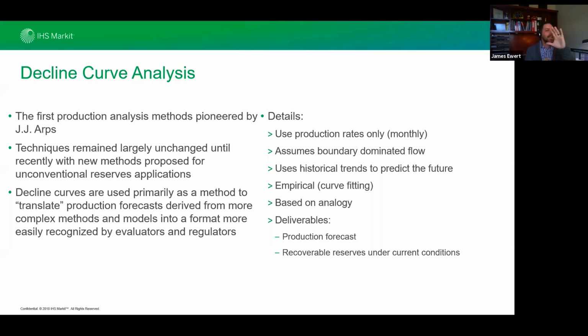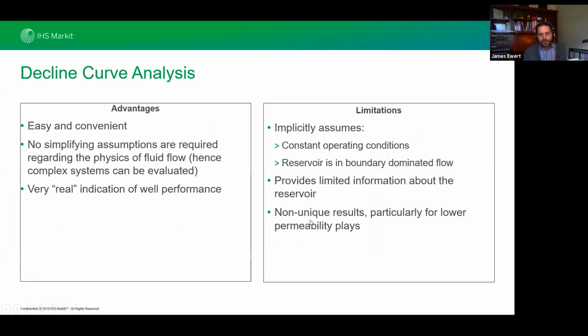And so you can start to take learnings from previous longer producing wells and apply them to newer wells and get a sense of what you think they're going to produce over their lifetime. So the advantages of decline curve analysis: it is easy and convenient. You do not need a whole lot of information to start putting decline curves through your data. You don't need to know PVT information. You don't need to know what the reservoir pressure is, anything like that.